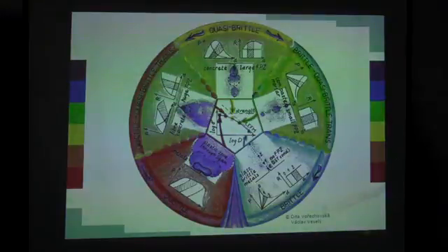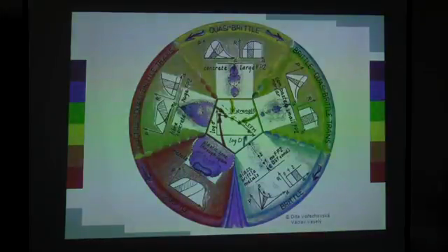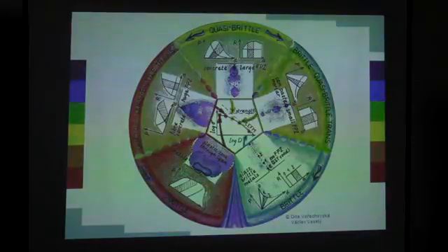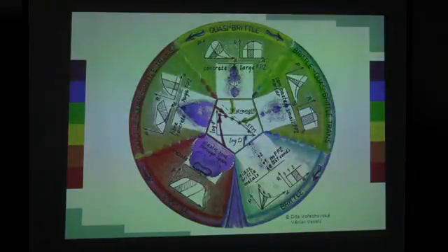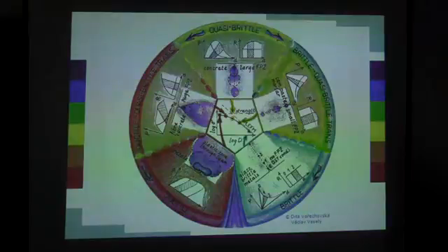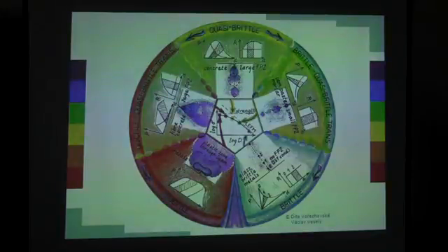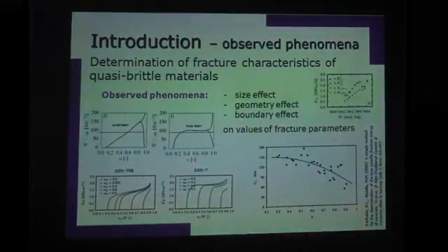So when we take into account brittle fracture, we usually don't speak about any large process zone because of small scale yielding conditions. And on the other hand, when we speak about, let's say, fiber concrete composites, we usually see a very large process zone, and only a limited value of the energy dissipated during the fracture can be assigned to crack propagation. More is assigned to some mechanisms that appear as plasticity.